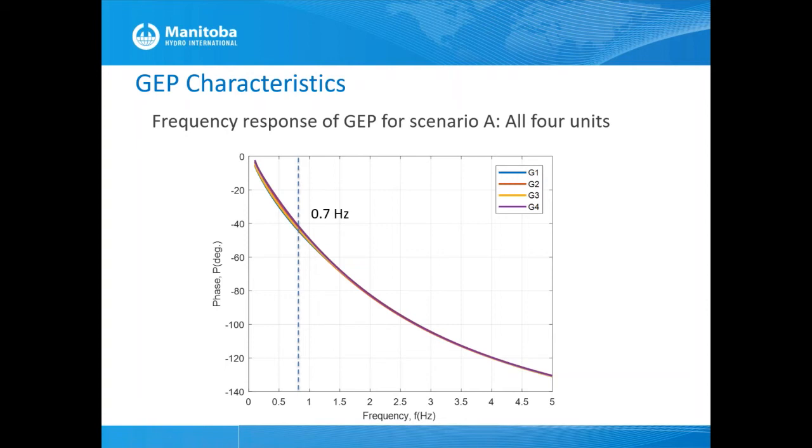But if you fully compensate this lag, then the torque component going from the exciter can be totally damping, and we might impact the machine's ability to keep synchronism because we reduce the synchronizing torque. So the rule of thumb is you don't compensate fully; you undercompensate, keeping a margin of about 20 degrees.